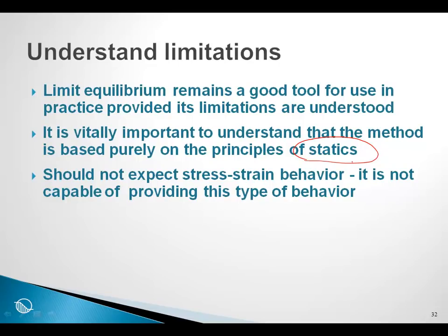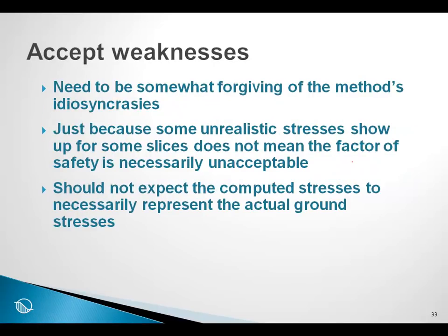Understanding this helps greatly with interpreting SLOPE/W results. Also, it remains a very good method, but you have to be somewhat forgiving of the method's idiosyncrasies. For example, just because some unrealistic stresses show up for some slices does not, let me repeat, does not mean the factor of safety is necessarily unacceptable.